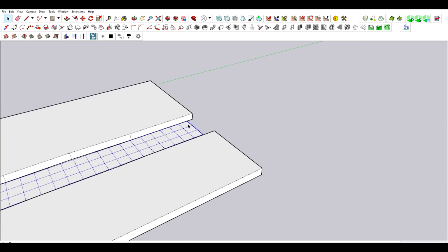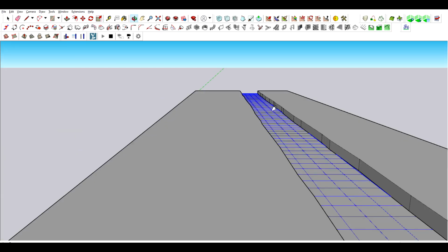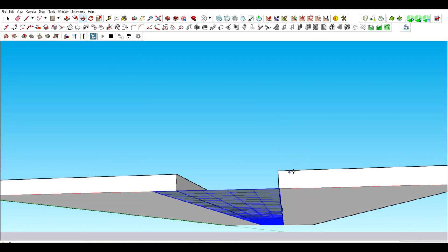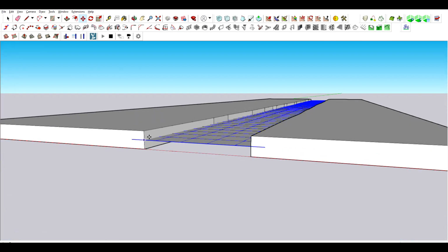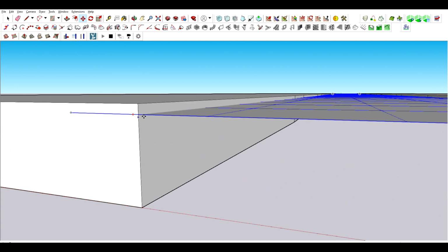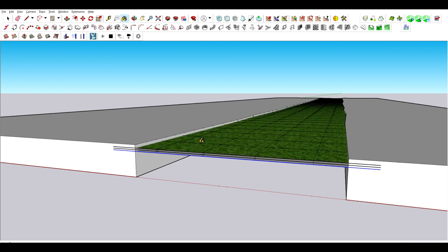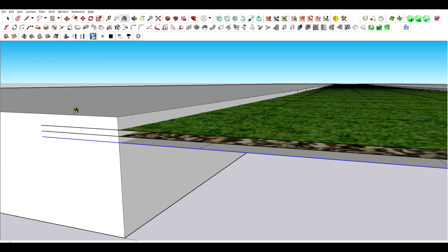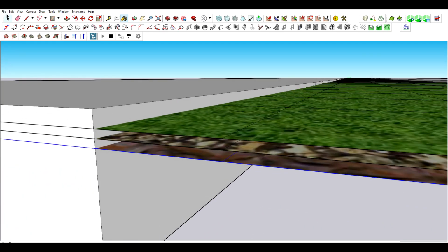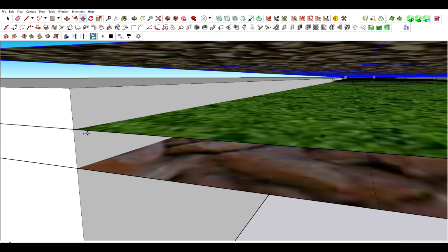Use the Sandbox tool to make the surface. I use 0.5 by 0.5 distance. Make two copies of it over each other. Place different ground materials on these three surfaces. I will show you the idea for this in Lumion when we apply 3D grass and landscape assets. Just to make sure, make it overlap with the pavement to simulate growth of grass over it.